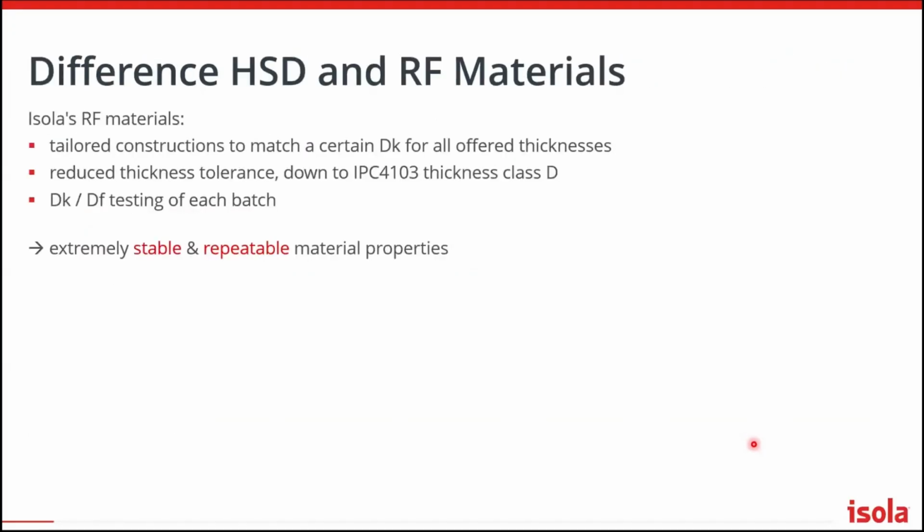Now, having spoken about the HSD and RF requirements, you will see that there are also materials that are tailored for HSD and materials that are tailored for RF. And the question very often is, what's the difference? What we on our end do in RF is that we have constructions that keep a certain Dk for all offered thicknesses. On the HSD side, that's different.